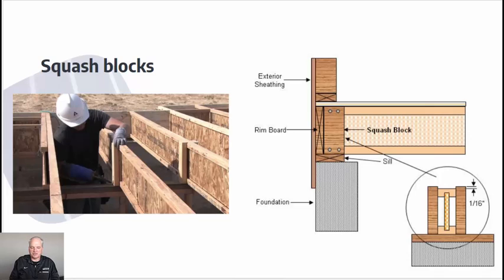The loads carried by floor joists, ceiling joists, and rafters are transferred through their endpoints to supporting walls and beams. The ends of these members must be able to react or resist these loads without crushing. AF&PA lists the required compression perpendicular to grain values for joists and rafters for various spans, on-center spacing, and loading conditions in its span tables. AF&PA's design values for joists and rafters list compression perpendicular to grain values for a variety of species. Just be sure the species design value exceeds the required compression perpendicular to grain value for your structural condition.